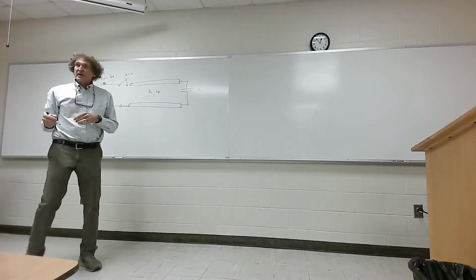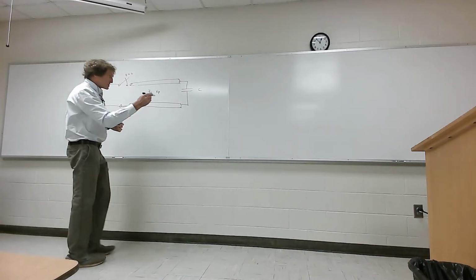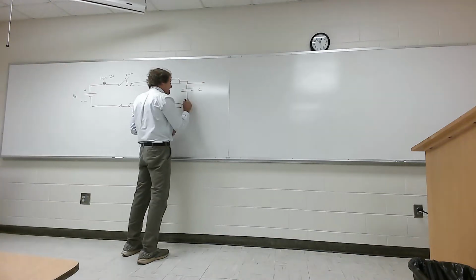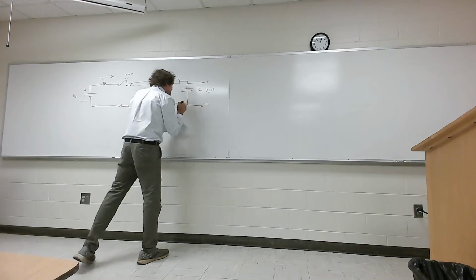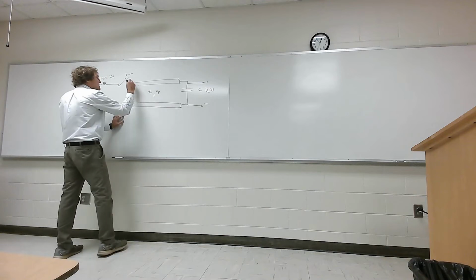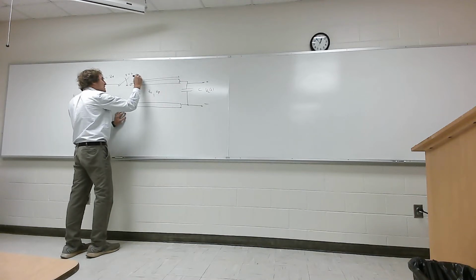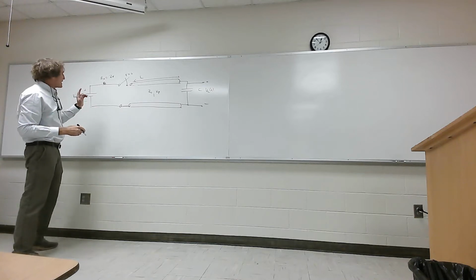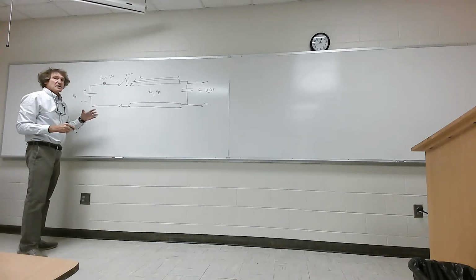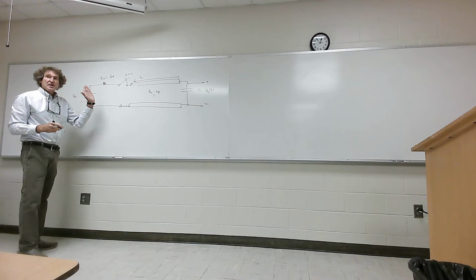Now what we're going to look at is what happens to the voltage, the load voltage over here, as a function of time. We're going to assume this line has a length L. And since I made RS equal to Z0, the reflection coefficient at the source will actually be 0, correct, class?